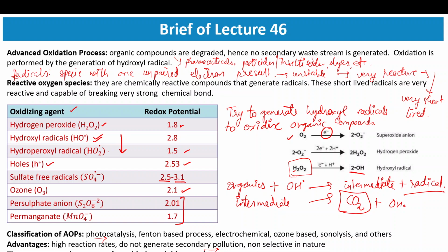Now, this treatment process is mainly used in your wastewater stream, right? So, for example, as biodegradable, if the ratio of BOD to COD is more than 0.8, then you can say the amount of biodegradable is much higher, right?